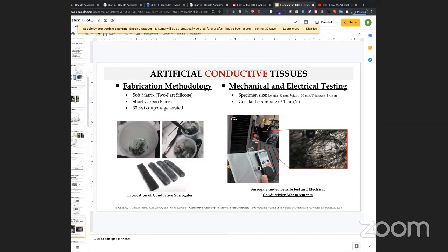So this is another innovation which we have created, and this is done using a proprietary fabrication technique which includes short carbon fibers, with very optimized length and volume fraction. By volume fraction I mean how many fibers within a certain area; those things are optimized, and we make this certain tissue property. Next slide please.